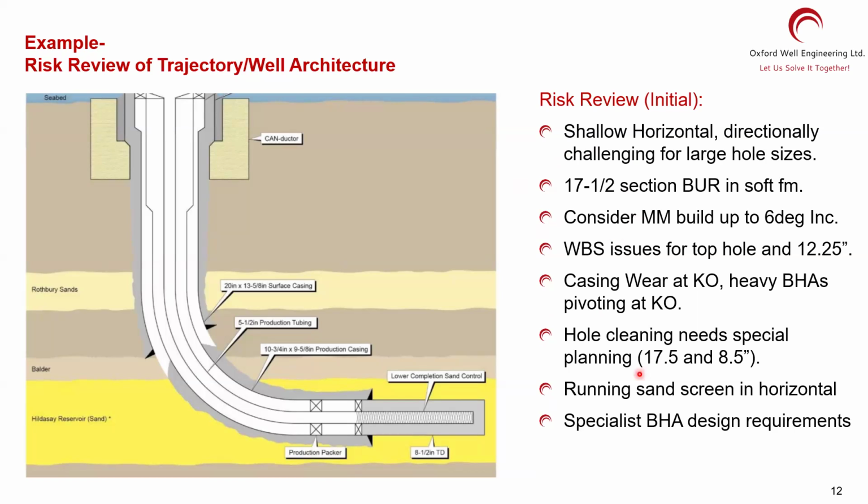You can say, okay, is 17.5-inch a problem for hole cleaning? Yes or no? Let's do the simulation. Let's check out the buildup rate in the offset well. Let's find out if it is directionally challenging for the large hole size. Let's check on those. So those are the first questions that come up when you have a trajectory on your hands. Yeah, this is a well from the North Sea, by the way.